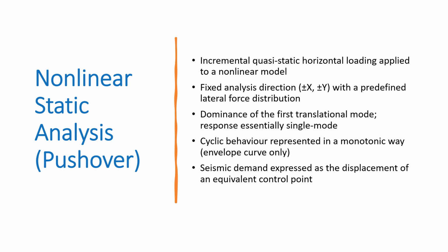The other main characteristic is that pushover analysis, a monotonic analysis, is an incremental analysis in which we apply a load pattern and control the displacement of an equivalent control point, following the response of the structure to these horizontal force distributions.